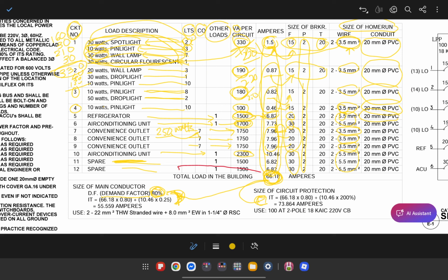You do not really use up all the outlets, or the total of 250 watts per outlet, or turn on all the lights that you have. It doesn't normally happen. So for purposes of being practical, we use an 80% load instead.